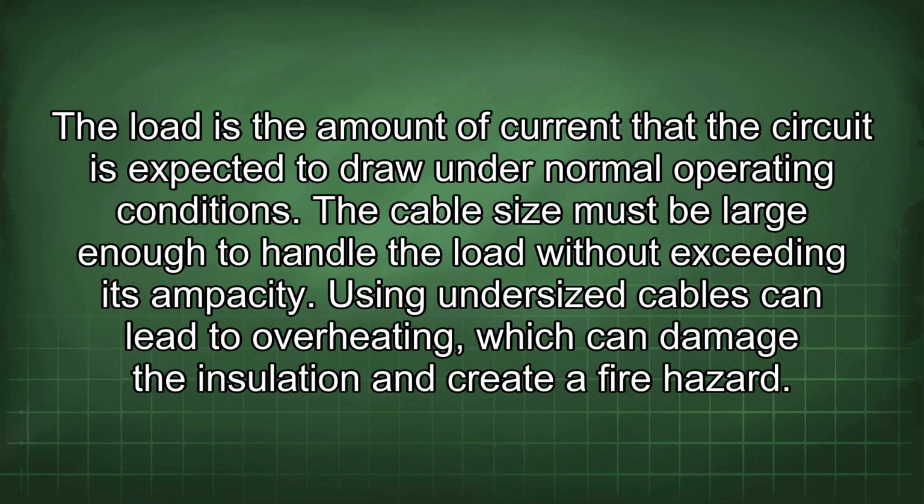The load is the amount of current that the circuit is expected to draw under normal operating conditions. The cable size must be large enough to handle the load without exceeding its ampacity. Using undersized cables can lead to overheating, which can damage the insulation and create a fire hazard.